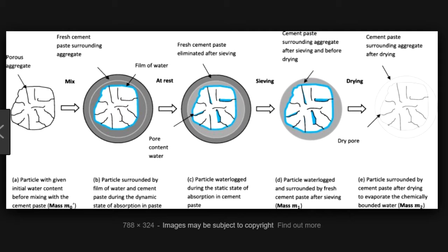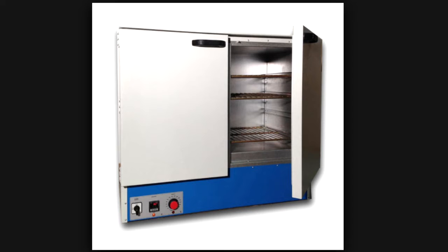For the coarse aggregates, the amount of sample collected was placed on a pan. Samples were then dropped on a splitter, which has 2 containers below it. Each container, more or less, should have half of the sample originally collected. One of the containers was weighed and placed in the oven to dry out.